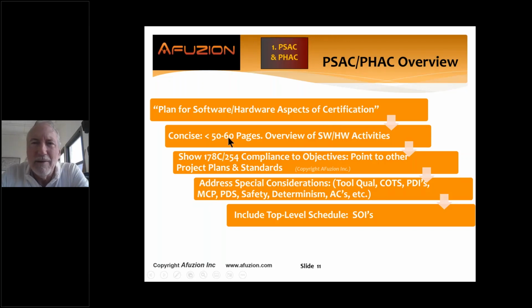Let me ask you a question. Raise your hand if you have ever seen a PSAC or PHAC more than 100 pages. Almost half of you. Wow. Almost half of you have seen a huge PSAC, PHAC. Folks, if you have a very complex distributed flight control system, maybe. But usually 100 pages means it's not a plan, it's a recipe, okay?